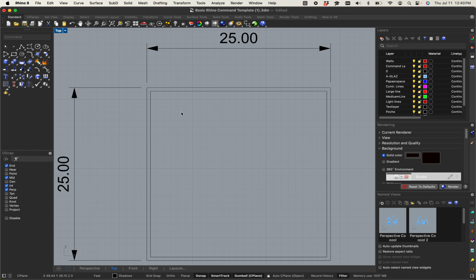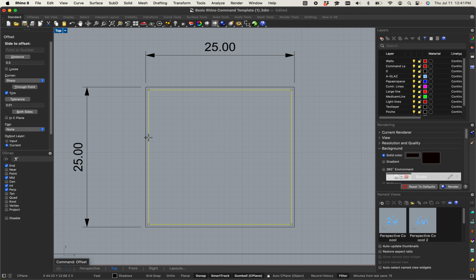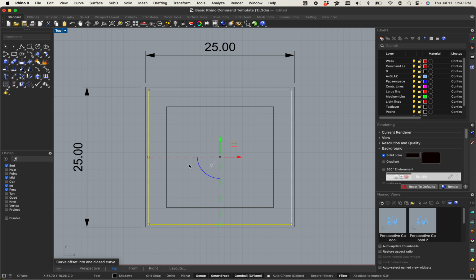Perfect, right? And now I can actually use the dimensions that I normally would doing my drawings. Let's get another offset in there. Maybe I get my stairs. Maybe I have kind of like a spiral stair going on. And I do want to model some stairs for us as well. So let's go ahead and offset. Let's say my stairs are 3 feet or 36 inches wide. I'm going to go ahead and put them on the inside.